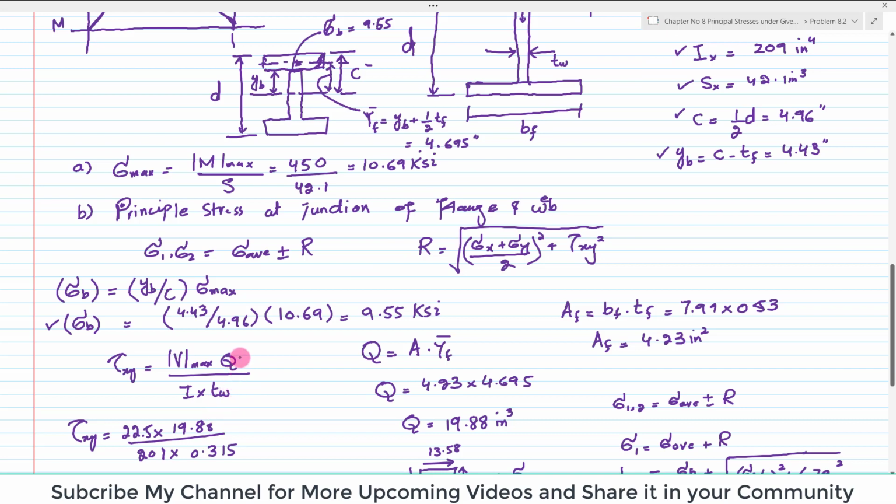So we will find Q, which is the first moment of area about the neutral axis. And we know that Q is equal to area times YF. So this is the area of the flange times YF. Area of the flange is equal to breadth of the flange times thickness of the flange. When you multiply both, you will get the area of the flange. Clear? Now what is YF? YF is, this is the flange.